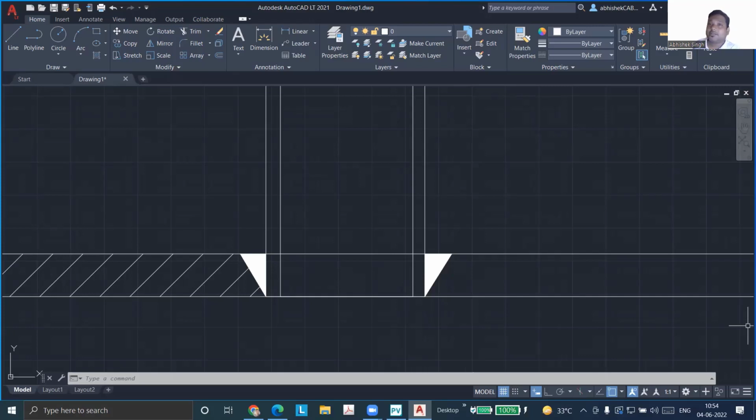based on UT, there is no joint efficiency, right? Our joint efficiencies depend upon RT. UT is kind of an alternate for RT, which you can follow. So there are two different methods, based on two different physics basics. Now for this weld, can I do RT? No, sir.